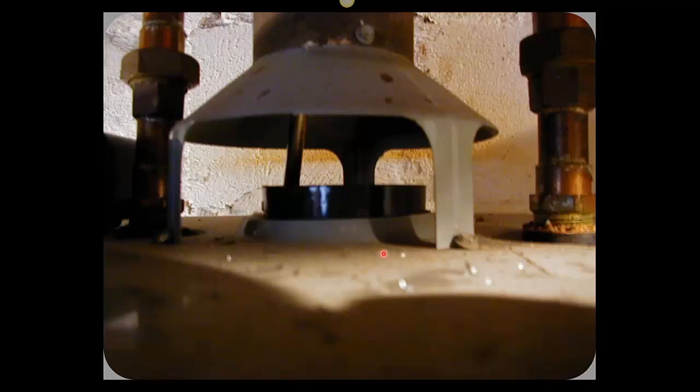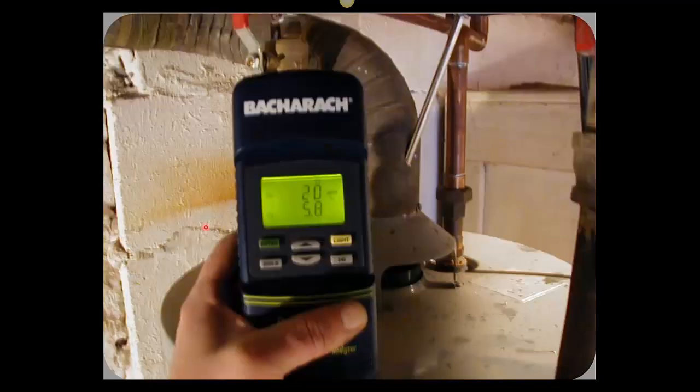You're going to see high O2, high excess air, and low CO production. In fact, in some cases, your O2 will be over 17%, and most every combustion analyzer out there won't even start doing math and giving you readings until the O2 drops below 17%. So again, we've got to be down in undiluted flue gases. So here's how they did this. They just simply drilled a hole here and angled the probe and got it down in there. You can drill a hole in the draft hood, stick your probe through there. Sometimes you can get your probe under the draft hood and get it in there.